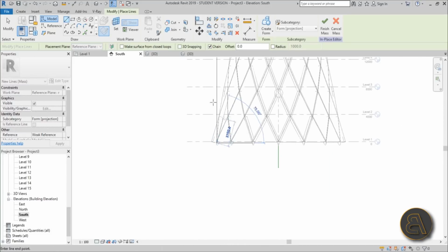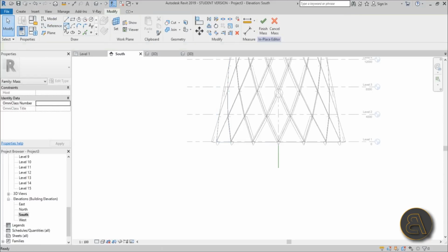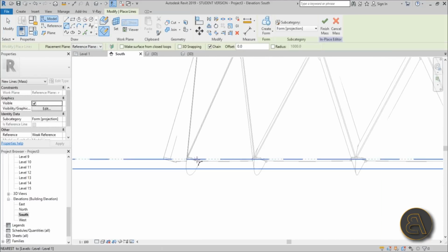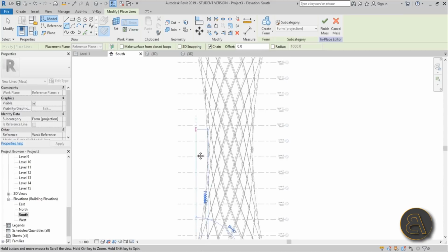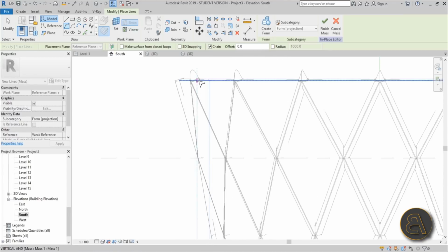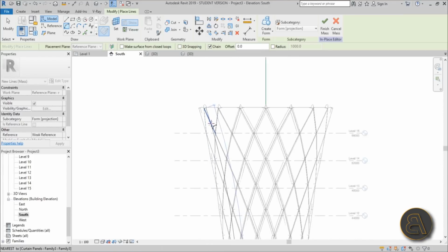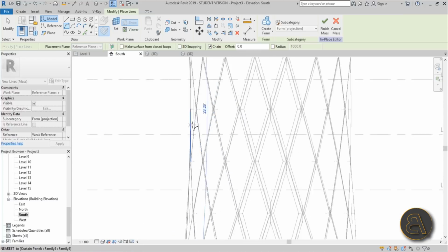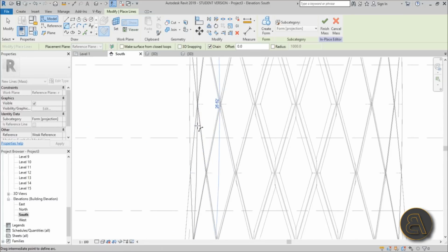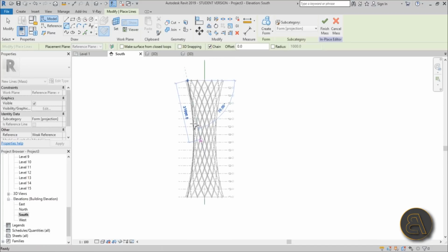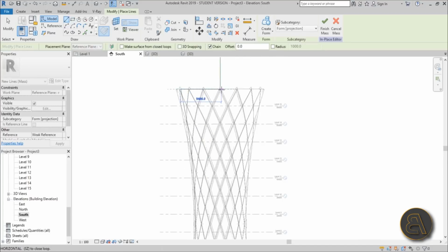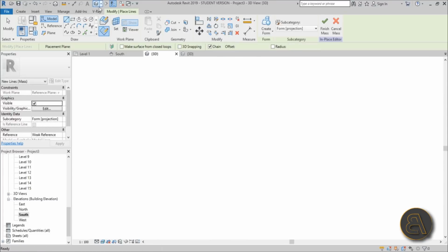finish it off here, or this should be actually an arc. Yeah, so let's start from here, go all the way up. Yeah, finish it like that, and then give it a little waist, as I said. So you finish it over here, and then you switch to just a regular line. You go straight to your reference plane, and you can go into 3D.